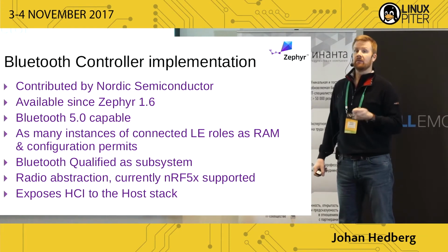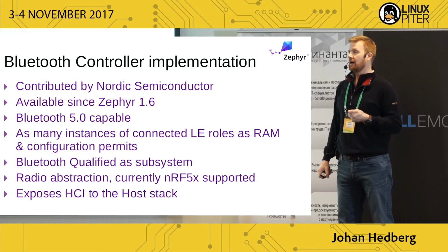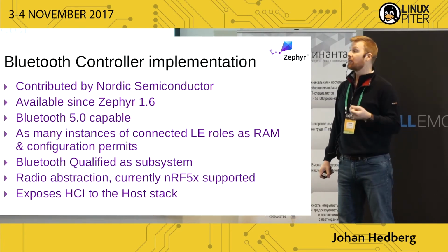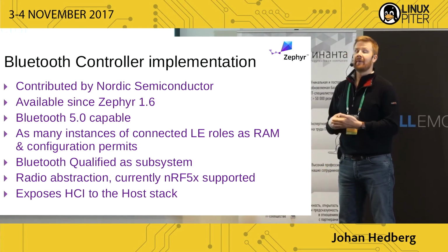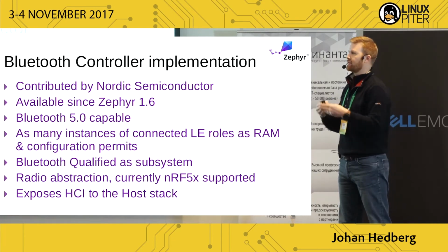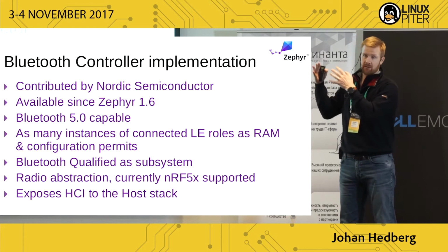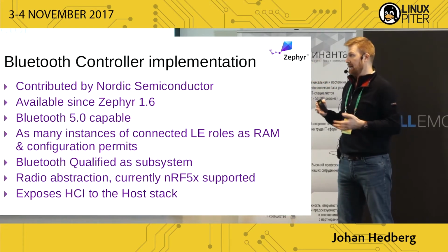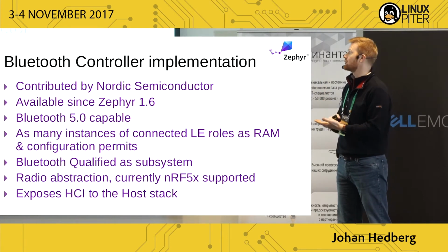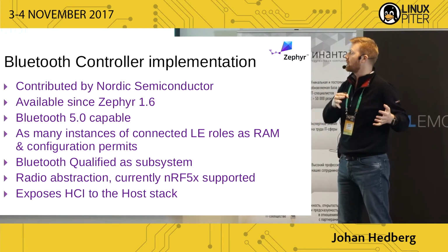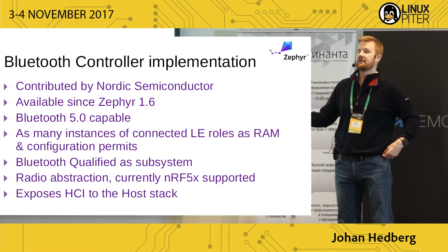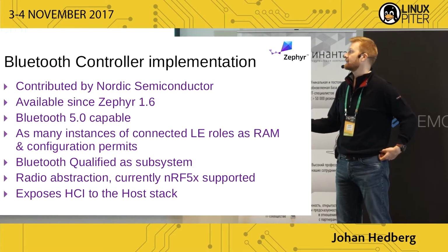Nordic actually did a full Bluetooth qualification of this. It was last week that they got the qualification listing. So you can make a certified product now with the Zephyr Bluetooth controller. You still need to qualify the host stack separately, which is a matter of running the test cases. We run them periodically, so you shouldn't get any issues. But the Bluetooth controller part is something that you can just refer to Nordic's qualification listing for if you want to make a product out of this.